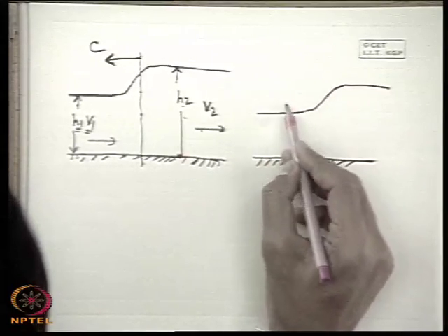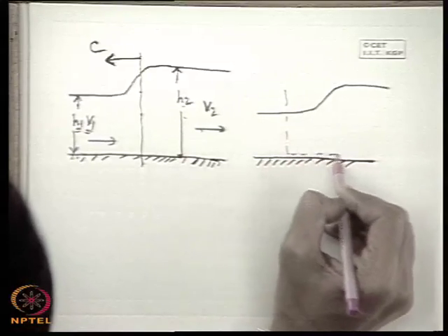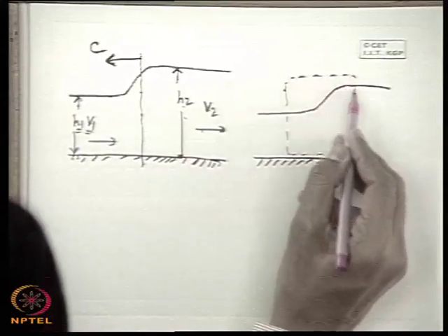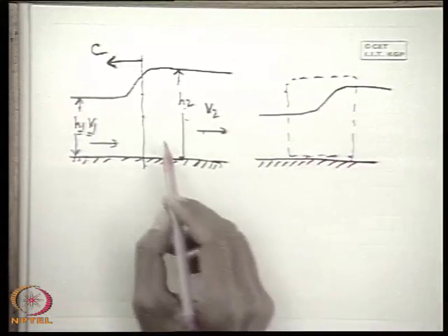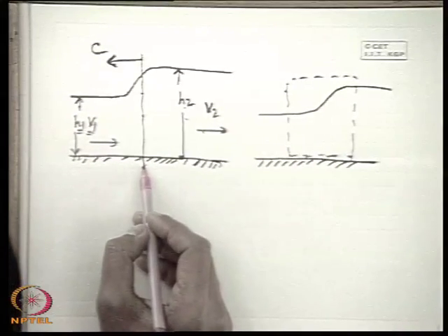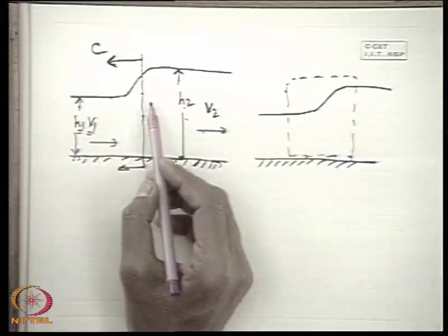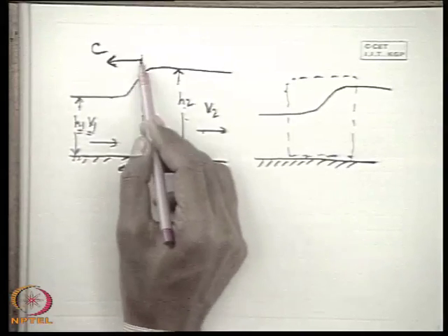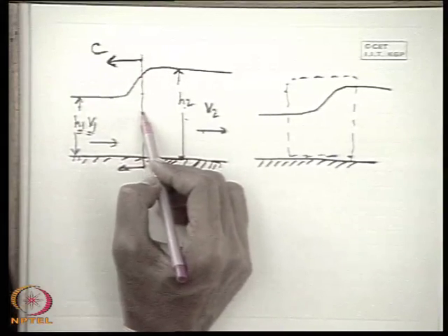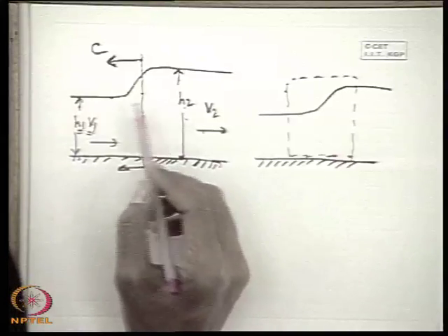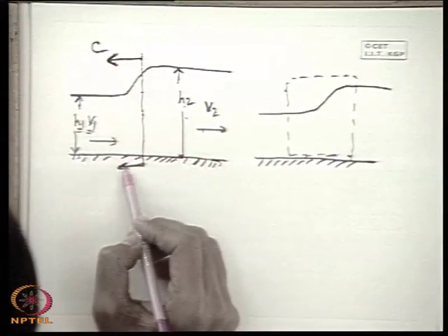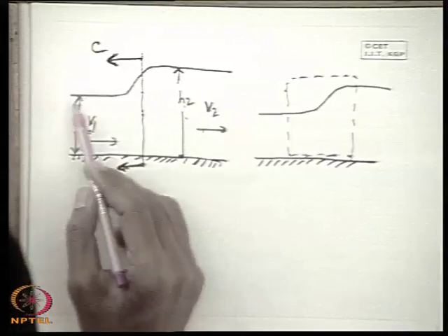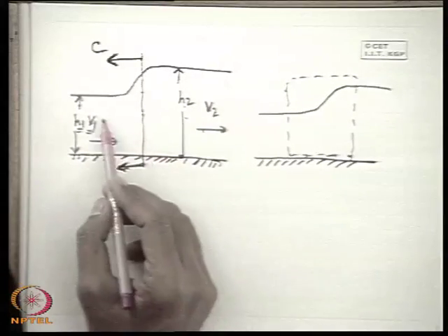We have already discussed that for this type of case, the control volume is considered to be fixed with the moving object. Here the moving object is the disturbing wave. This is because if we analyze with respect to this wave, the things become steady. Otherwise the things become unsteady.